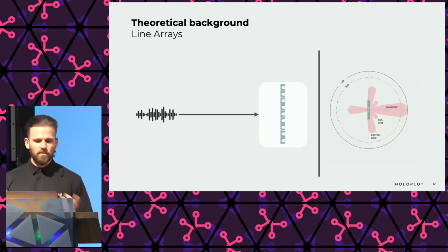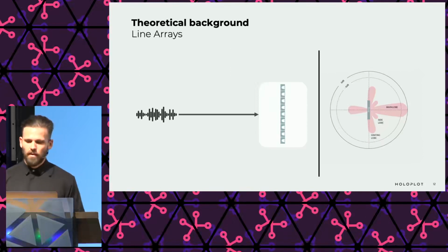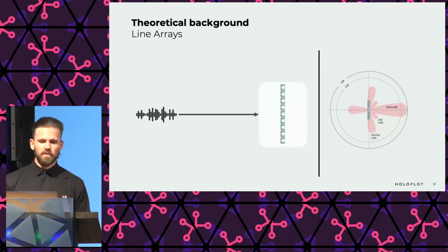Or alternatively, we could build many loudspeakers in that array with different sizes and dispersion patterns, and also tilt them mechanically with different angles so that they effectively cover a wide audience area. One example of this type of loudspeaker, probably you're already familiar with them, would be these, also commonly known as banana-shaped line arrays, or also J-shaped, that effectively combine the different loudspeakers mechanically tilted differently with different dispersion angles.